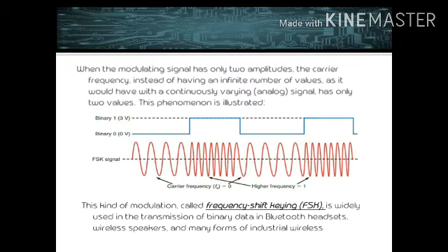Frequency shift keying, or FSK, is a frequency modulating scheme in which digital information is transmitted through discrete frequency changes of a carrier signal. The technology is used for communication systems such as telemetry, weather balloon radiosondes, caller ID, garage door openers, and low frequency radio transmission in the VLF and ELF bands.